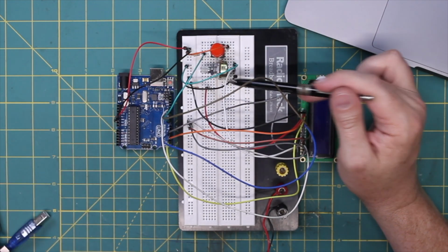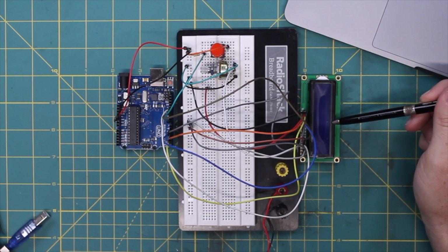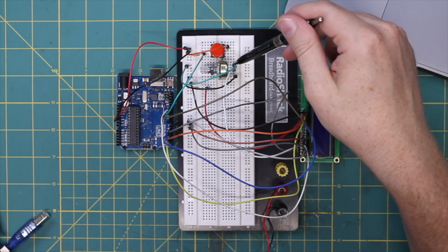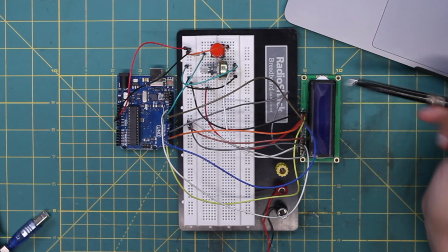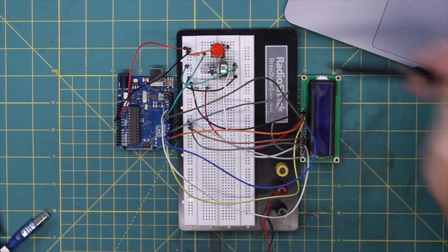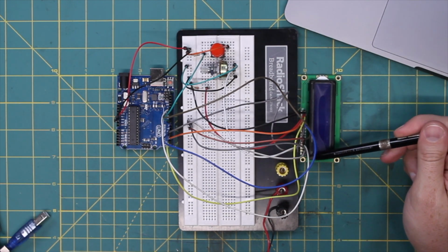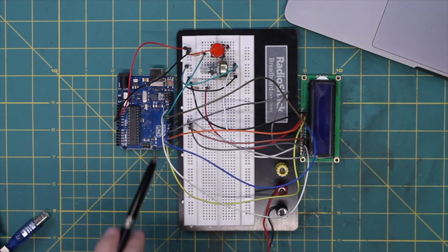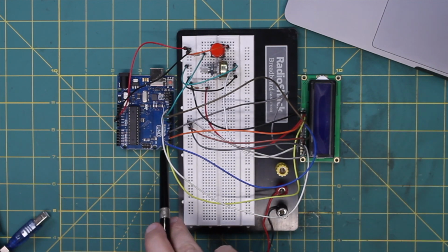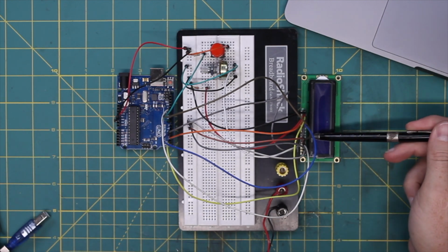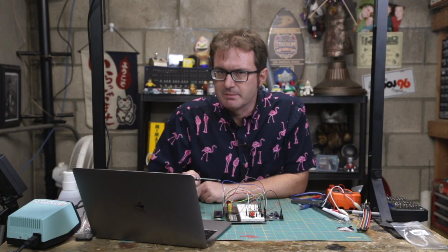We have a potentiometer connected to the LCD, as well as power and ground, to control the brightness on the LCD. And then we have a series of pins on the LCD connected to the Arduino and to power and ground to control the data moving from the Arduino into the LCD. I'll put much more detail about this in the show notes down in the doobly-doo.